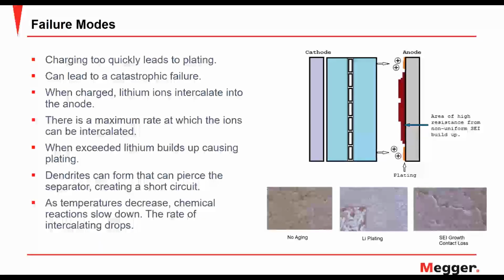That's why it's very, very important for lithium-ion batteries to have a battery management system to give a different charging rate at different temperatures, as at different temperatures they will not accept the constant charging used by a normal charger. A battery management system is thus very important to prevent this type of failure.